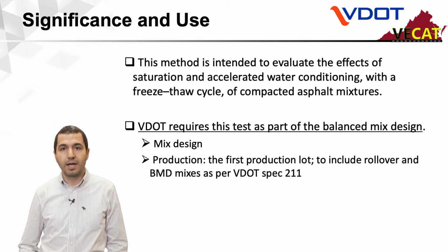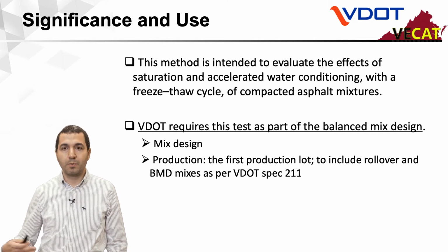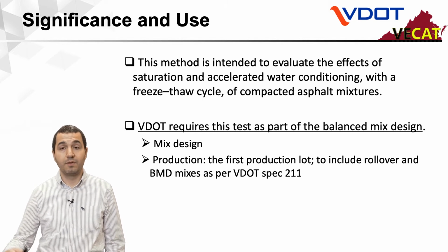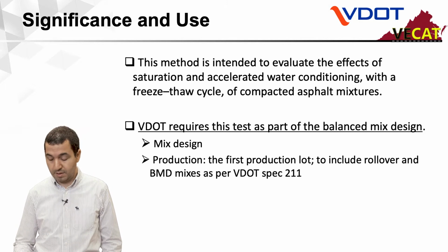mixtures. As I indicated, VDOT requires this test as part of balanced mix design process, as referred in Spec 211, during mix design and production. And for production, it's only for the first production lot that testing is required for this test.